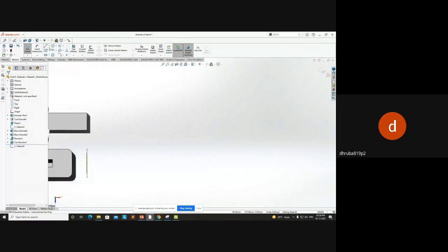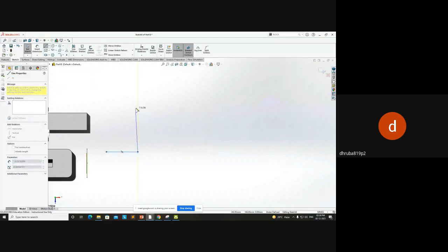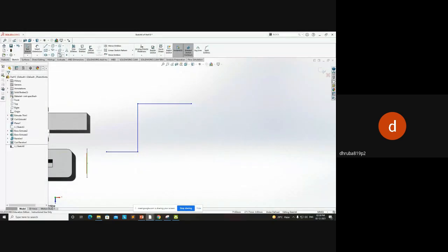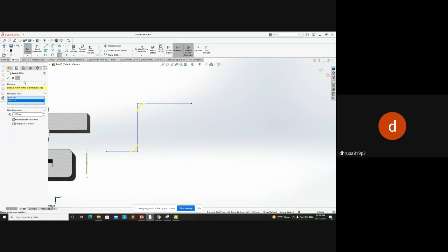I'll add some fillet over here. Let's add a fillet of 20, one over here, another over here. Press OK.